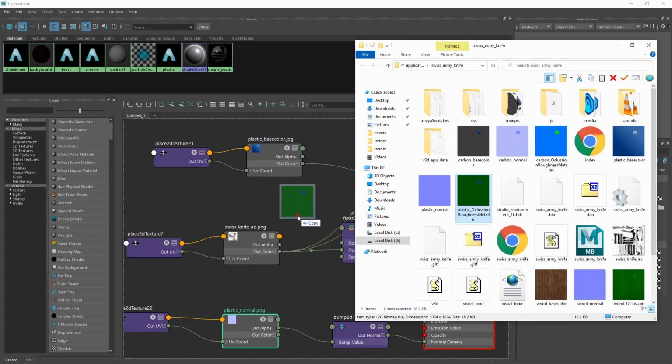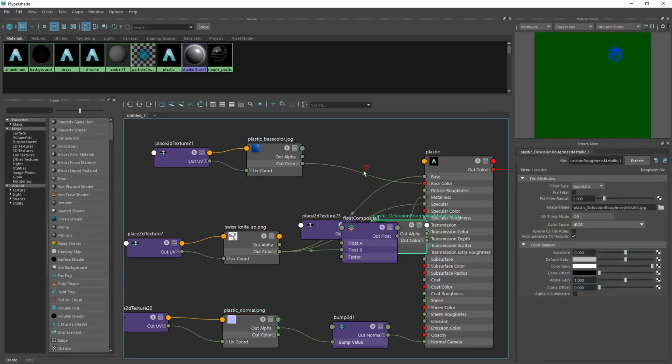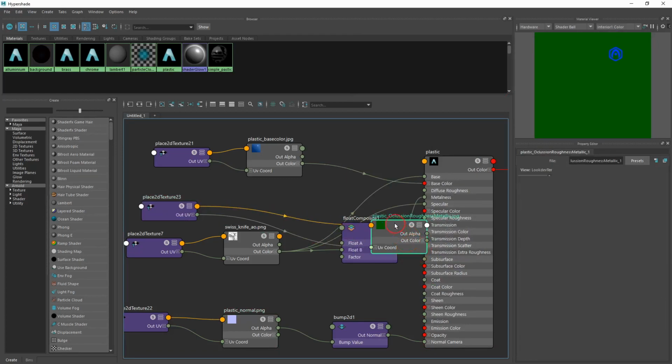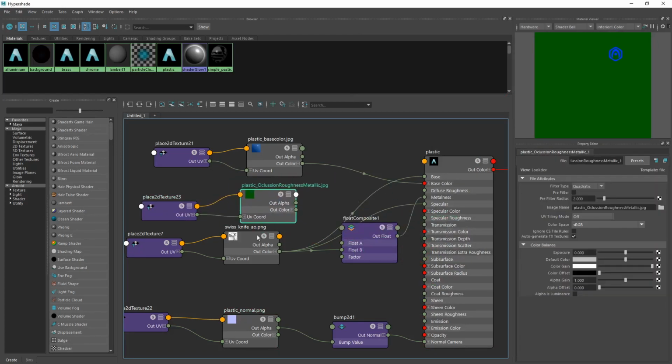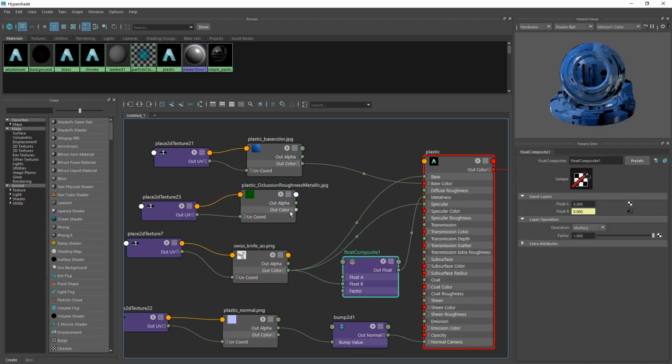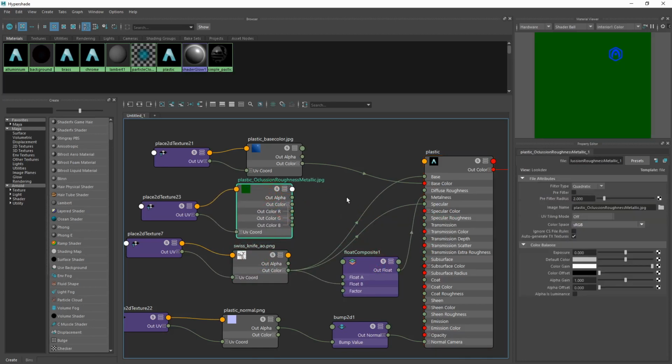Finally, we add that single texture in the channels of which we packed the roughness and metalness information. Now we need to retrieve this information from the channels. Remember that the red channel is empty. It is intended for occlusion, but we have a dedicated texture for that.